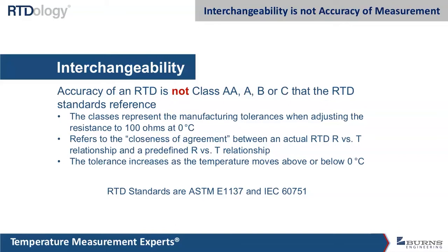And the two standards that are followed are this ASTM and the IEC. So they just lay out the groundwork, the playing field of what an RTD should do and how it should perform. They're not real stringent, and you're going to find a whole variety of RTD performance that all meet the standard, but there's others that far exceed what the standard is. You typically pay a little more for those, but you do get a lot better accuracy, stability, repeatability, those kinds of things.